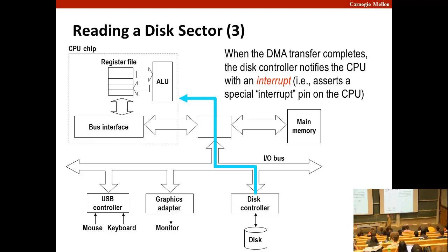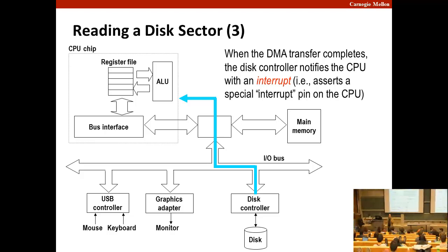Does that make sense? This is good because it offloads work from the processor. It's bad in some nominal sense because it means two different processors are competing for the bus. And you can get some contention, where the main processor is trying to use the bus for one thing, but the DMA controller has it for another.